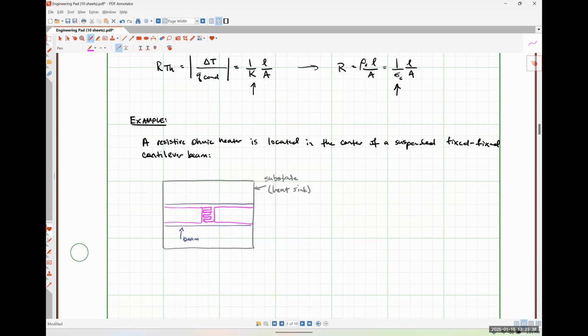The reason why it's a serpentine section of metal is so that we can have a very long length with a very small cross-sectional area, so that when we push current through it, it heats up a lot because the resistance is very large. Okay. So this thing right here is our heater, and this guy right here is just a strip of metal.